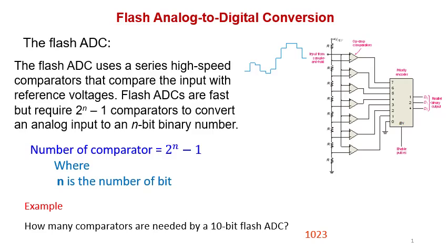It's time now to talk about the analog to digital converter. An analog to digital converter is a circuit which will convert the sampled signal to digital. But keep in mind, there are many circuits and techniques used for that purpose. Here we are going to study only the flash type, or flash analog to digital converter, which depends on comparators.